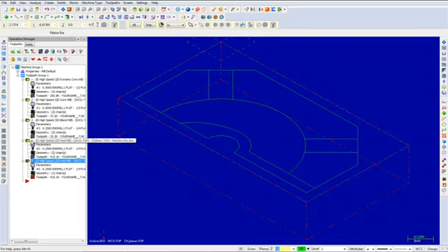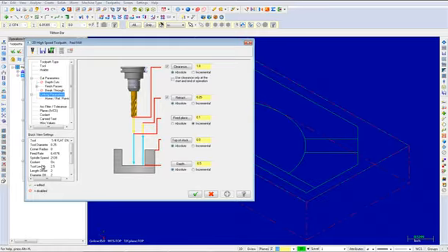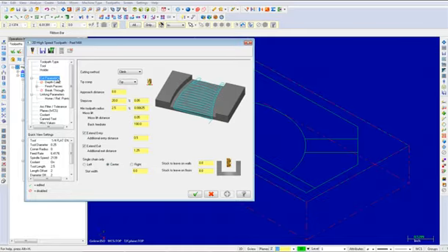Now pick the parameters in operation number 5. Select the cut parameters. Change single chain only to left and enter a slot width of 0.5.